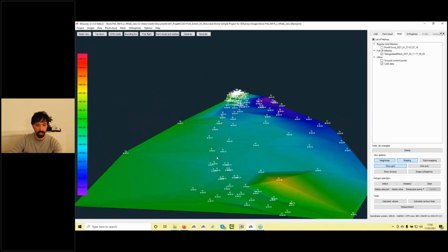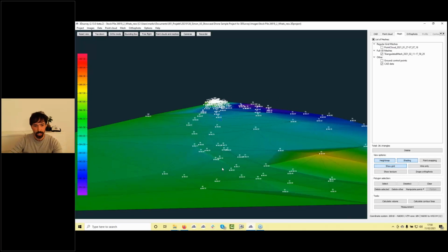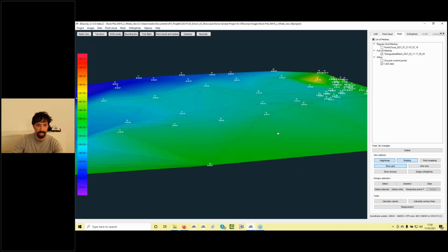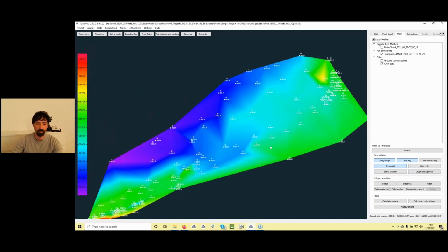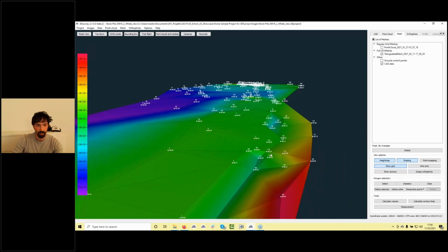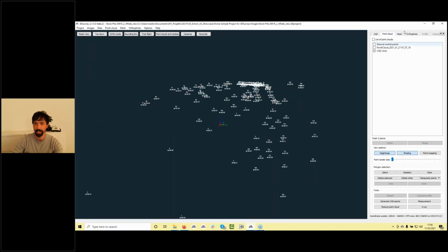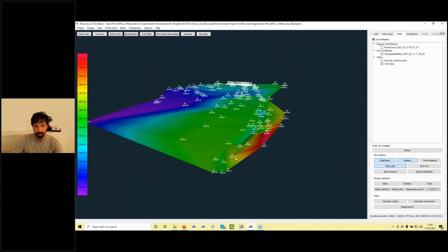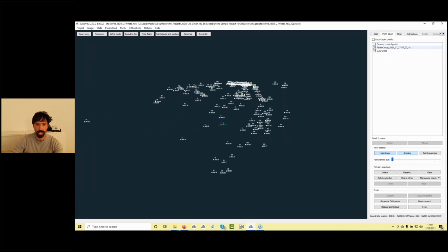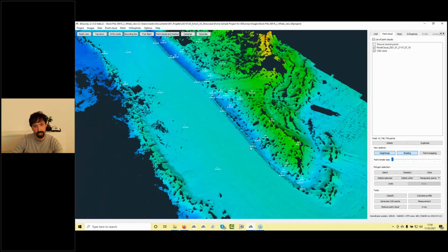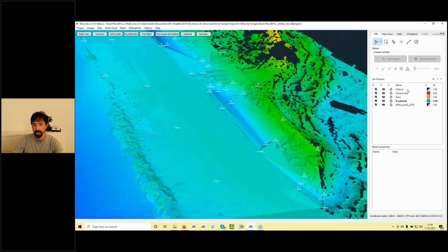You see the triangles are quite big here, but when we measure with the total station or GPS, we measure every 5 meters or something like that. So this is pretty decent. Then what I could do in addition, I could create some break lines. So maybe because I see the mesh was here not perfectly connected, probably we have, okay, like here, what I could do if I go back for help, turn my point cloud on. This is from the new measurement, but probably in this part nothing changed, and go back to CAD.